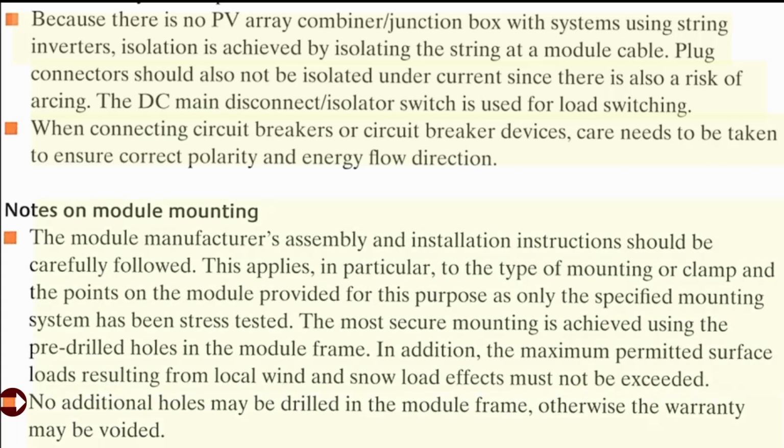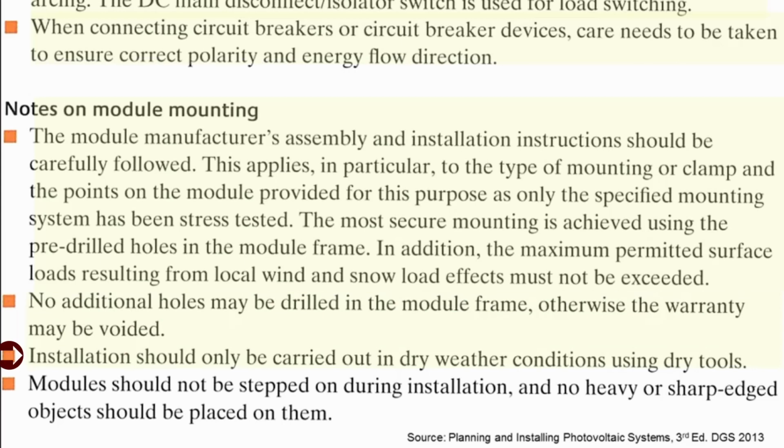You should not drill additional holes in the module frame, as the warranty may be voided. Installation should be carried out only in dry weather condition, also using dry tools. Usually, if you want to avoid the current of the modules being carried, you do that at nighttime. Modules should not be stepped on during installation.